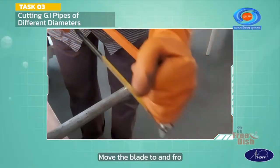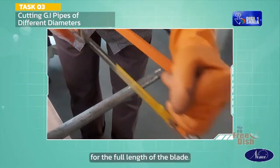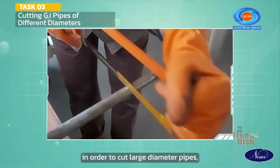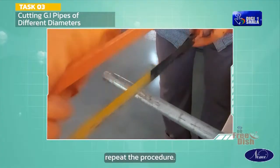Move the blade to and fro on the marked groove at 40 to 50 strokes per minute for the full length of the blade. Ensure to use a coolant while cutting. In order to cut large diameter pipes, rotate the pipe after cutting till half the depth and repeat the procedure.